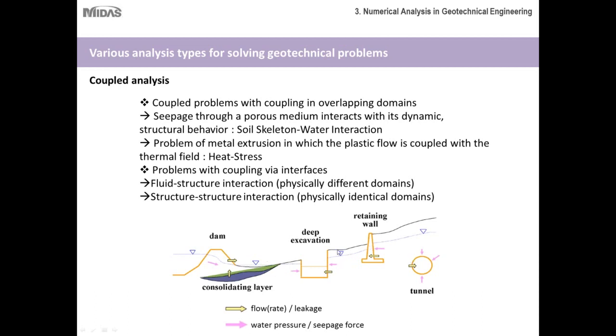And essentially coupled analysis is just taking two different analysis types that are interrelated and using them for the same project. So let's take a look at this dam here. As you can see, this dam has a water level that's much higher on this side than on this side, so naturally there's going to be some flux taken into account. So you'd have to do a seepage analysis.